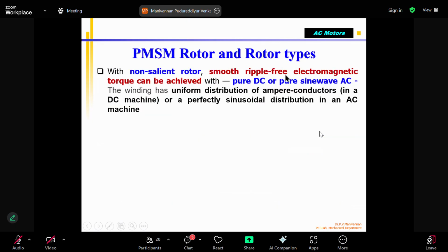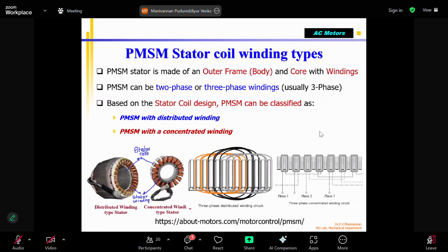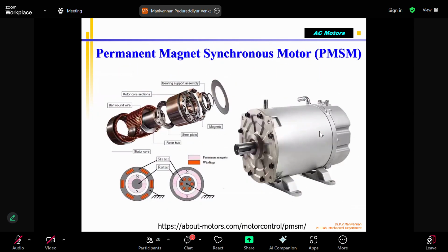Yeah, we were talking about the permanent magnet synchronous motor type of AC motor. Its construction, we just started yesterday, correct? Very simple. It is a synchronous motor, but the rotor is a permanent magnet. So a lot of complications are reduced: supplying DC power, slip rings, and the resulting complicated mechanical weight. Reducing all this is an advantage.